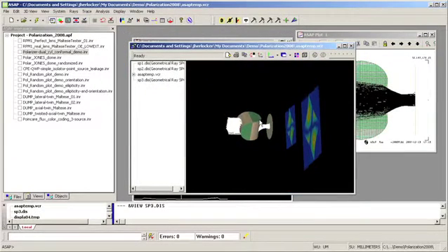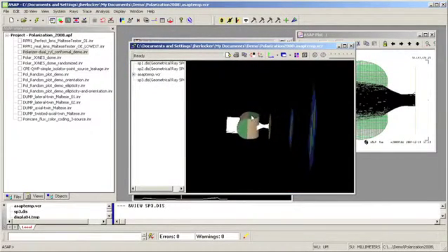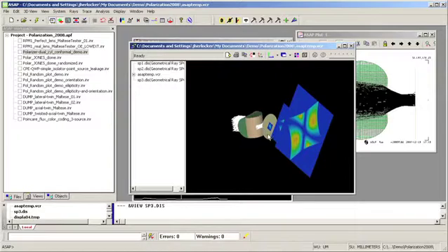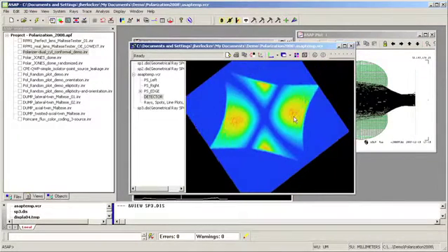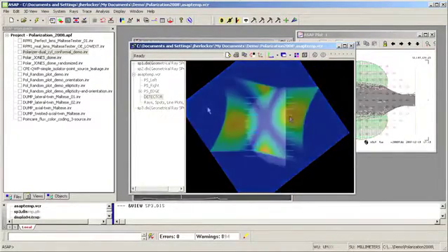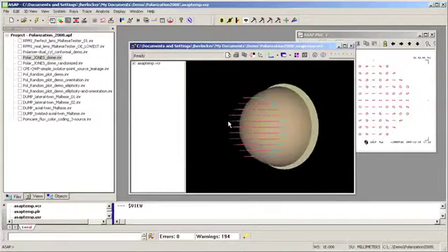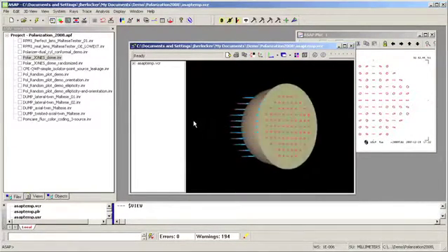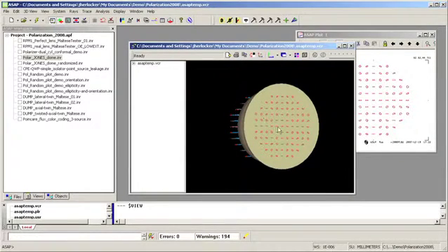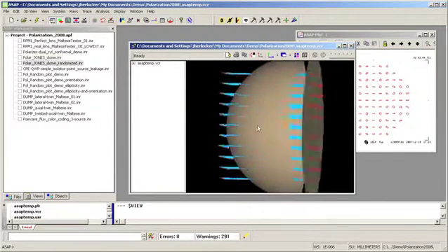A distorted form of the Maltese cross pattern can be produced when cross-cylindrical lenses with skewed conformal polarizers are analyzed. Another new polarization device type, the Jones element, can be used to simulate a polarization retarder. For instance, the effect of a conformal quarter-wave Jones retarder on a linearly polarized input may be assessed.